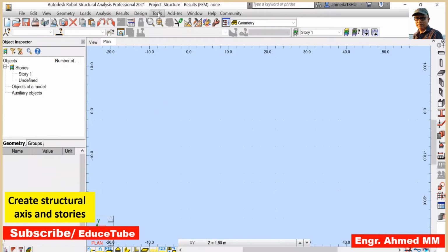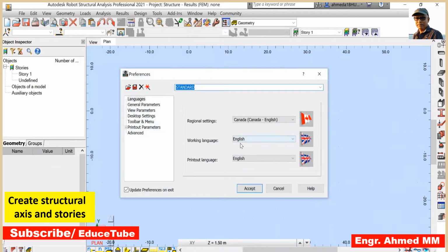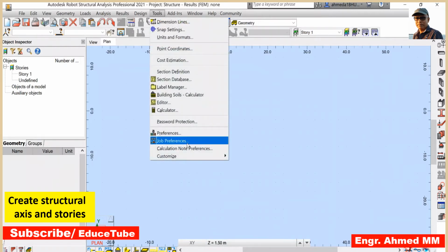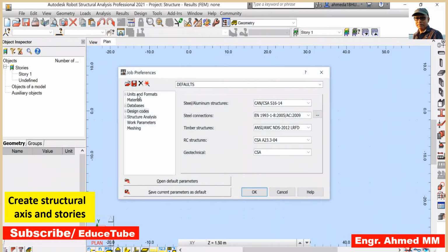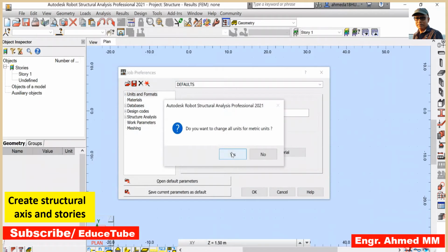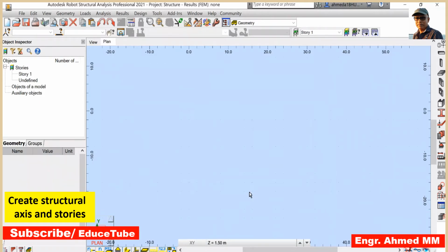So how to do that? Click on Tools, Preferences, English, accept it. Again Tools, Job Preferences, click on Units, Metric, so okay, finish it. So we are done with this part.